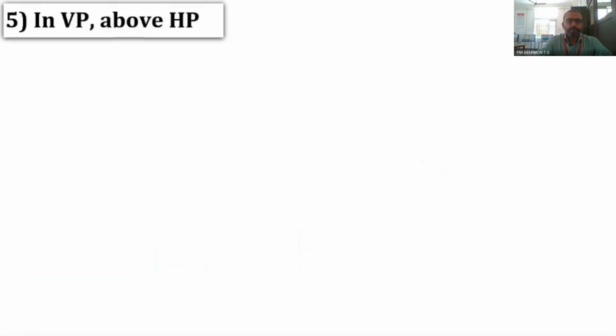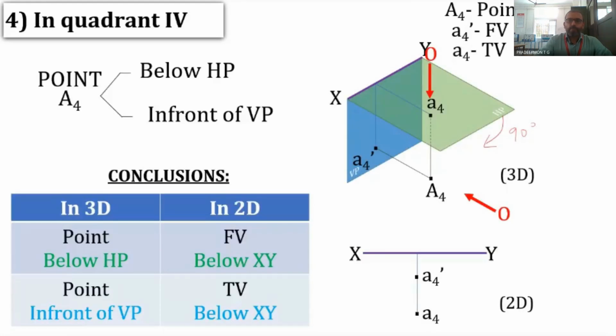Sorry, by the way, I actually forgot one thing to say. When you draw the XY line, it should be dark and thick. The XY line should be a dark line as well as a thick line. But this projector line should be very thin and very faint. It should be visible, but very thin.